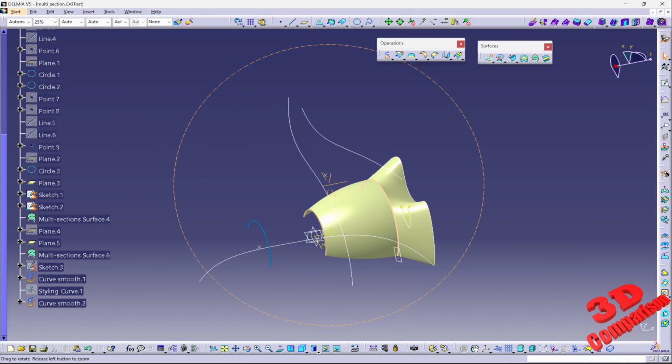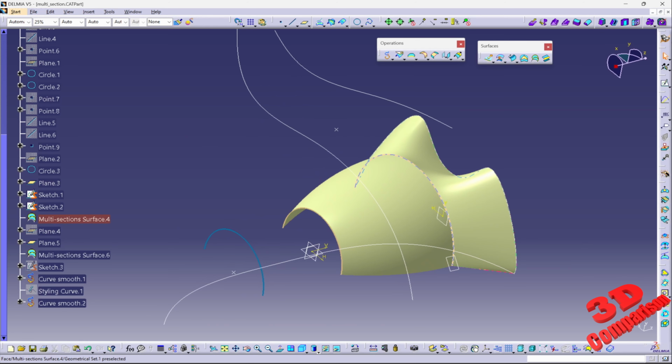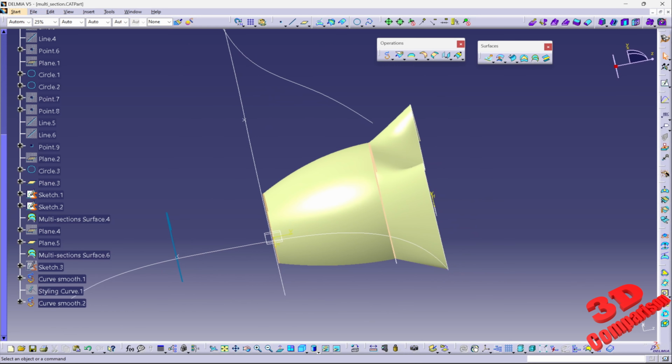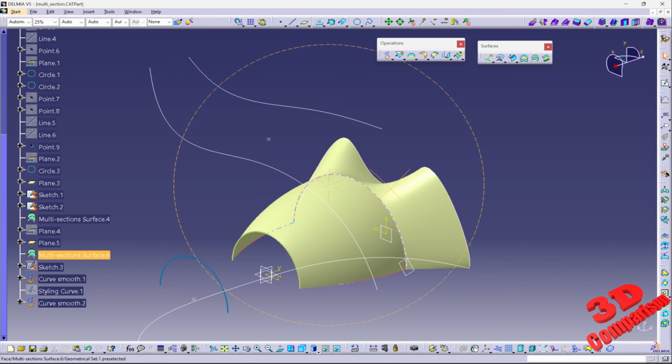Okay, so I hope you enjoy this kind of content. It would be nice in order to define those surfaces directly without any tangency problems, but usually in most cases you will end up with sections like this that you will later have to do some edge filleting in order to have those tangencies enabled.